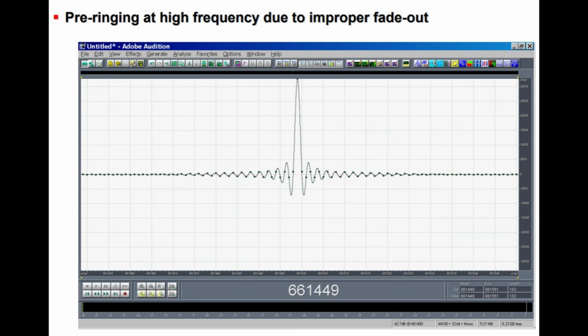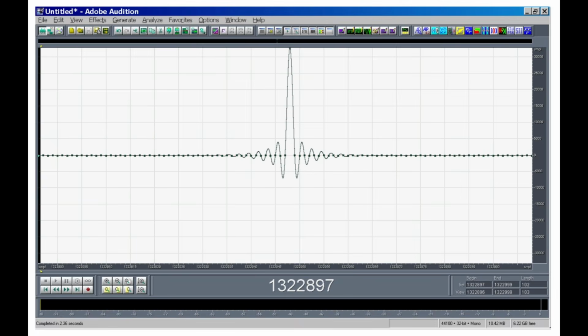Specifically, this picture illustrates the pre-ringing effect produced by deconvolving the test signal directly without it passing through the system under test. Always continuing with Farina, the situation ameliorates significantly if we remove the fade-out. The following figures show the results obtained with exactly the same settings as in the previous case, but with a length of the fade-in set to 0.0 seconds.